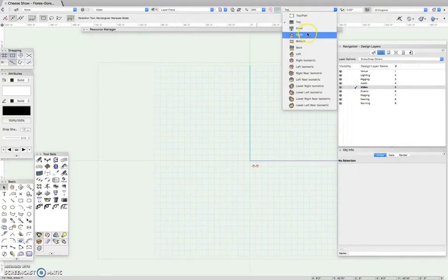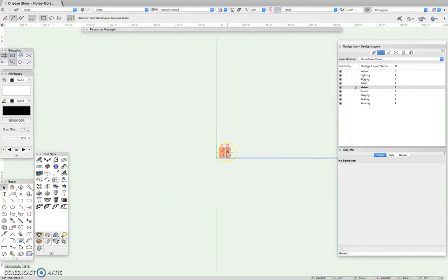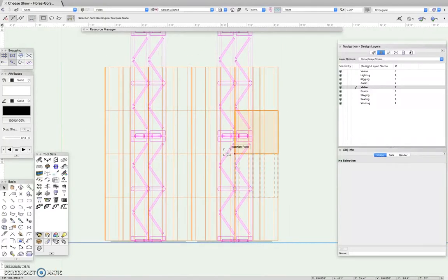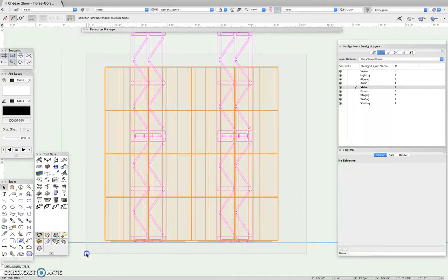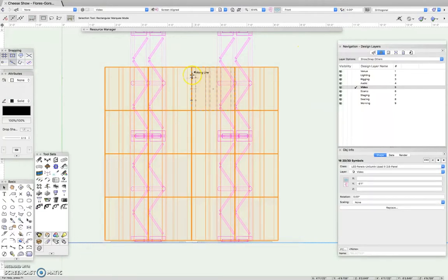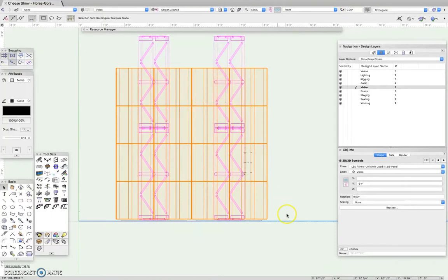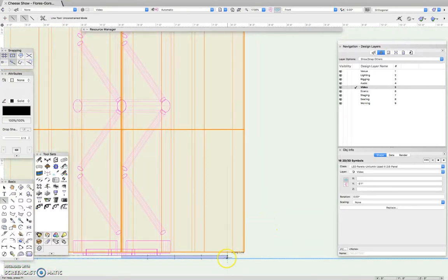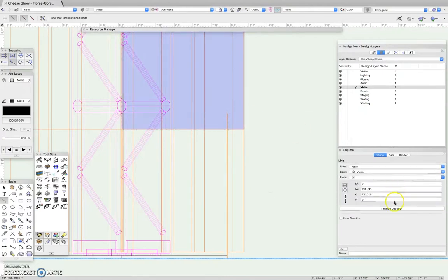So if we go back to our front view, it was requested that the top of the wall be 8 feet off the ground. Let's see here. How should I do this? I can draw a line going from here straight up. Make the Y distance 8 feet.